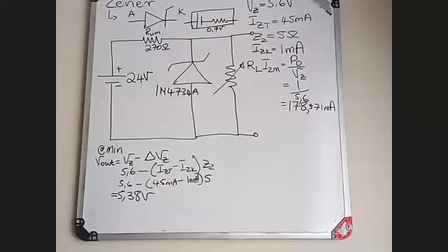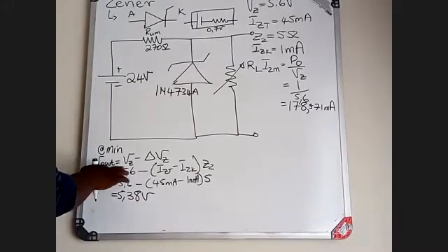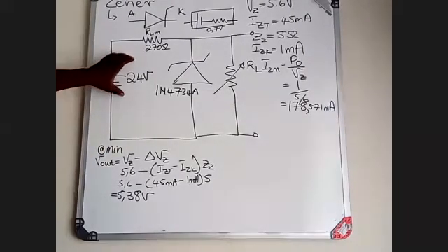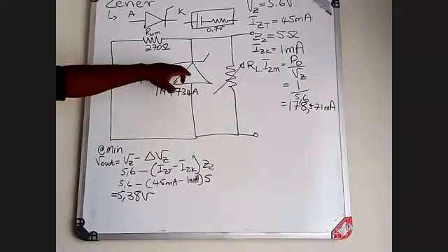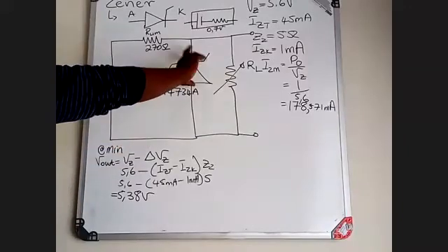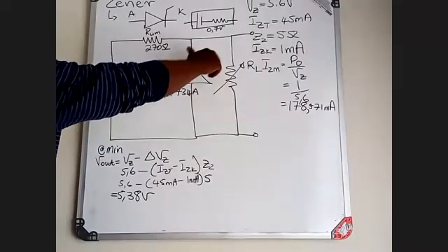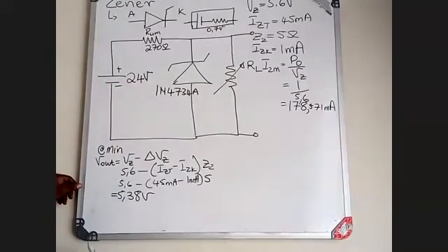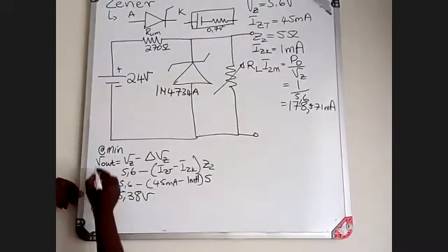Okay. Now, once you get this, that is your V out at minimum. So for this given voltage, when you start regulating, you're going to start regulating your Zener output voltage at 5.38, which means this is the minimum voltage that it can start regulating with.